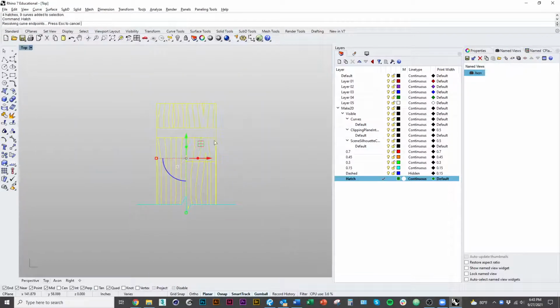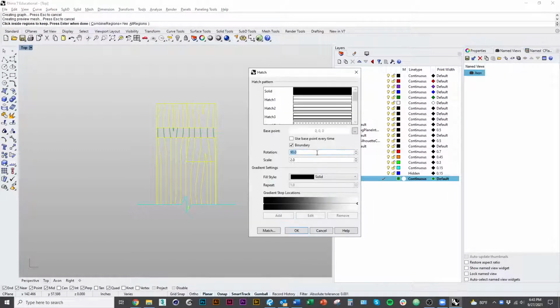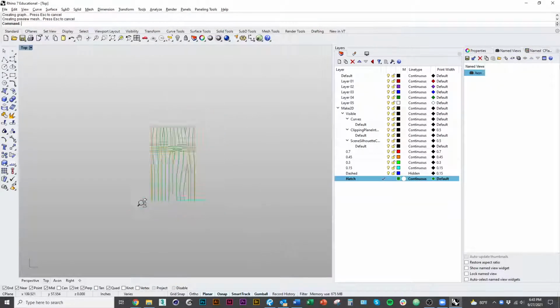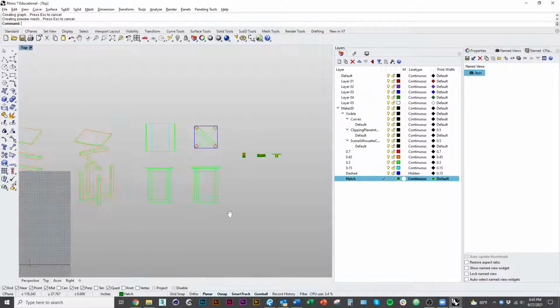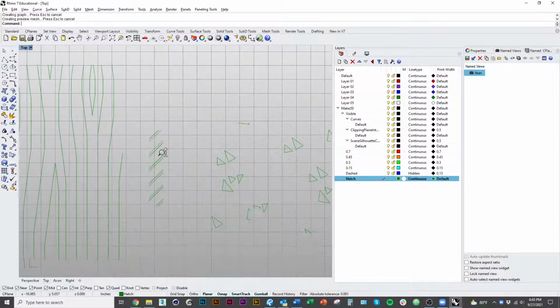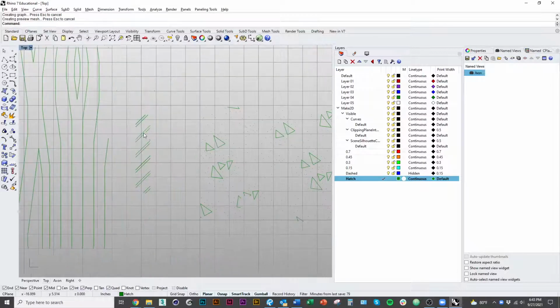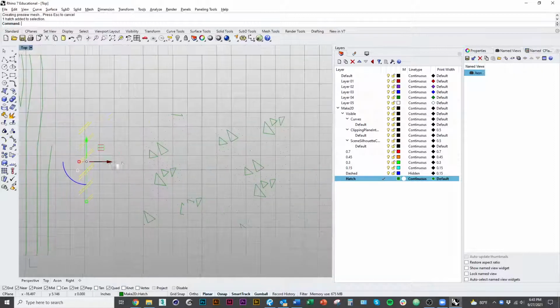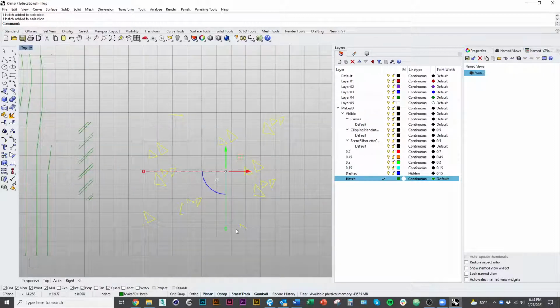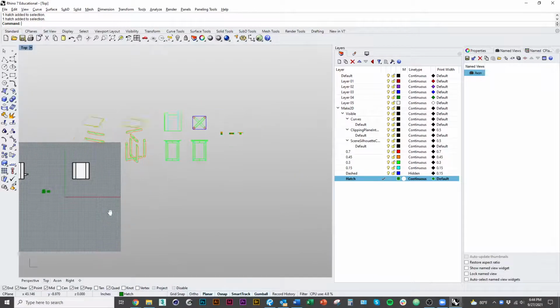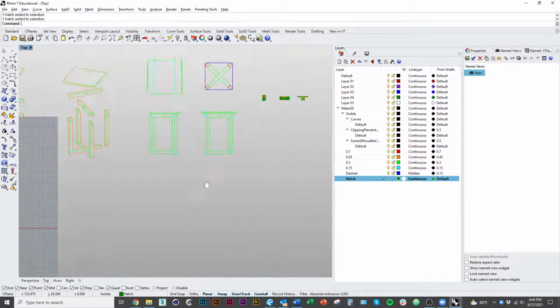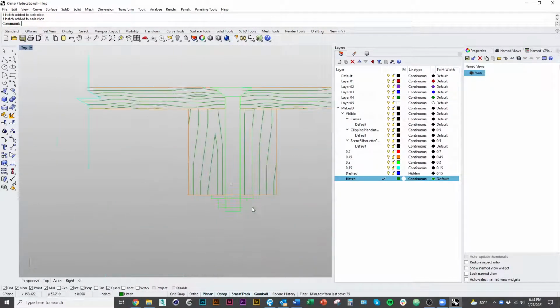Those are actually the same orientation, and then this would be, and we'd make that maybe lighter or smaller scale. There we go. And then finally, the typical hatch pattern for wood, we can use that like a wood grain pattern. This is a typical hatch pattern for steel. So 45 degrees double line. This is pretty typical for concrete. It's kind of gravelly with the crazy triangles. We're not going to use any of them, but they're there if you intend to indicate any of those materials.